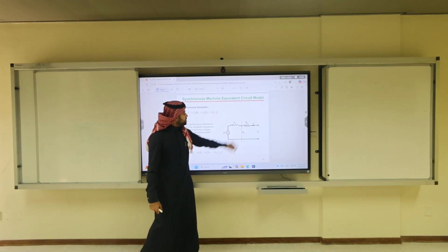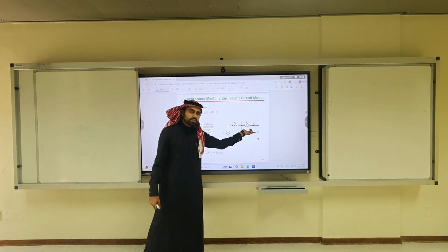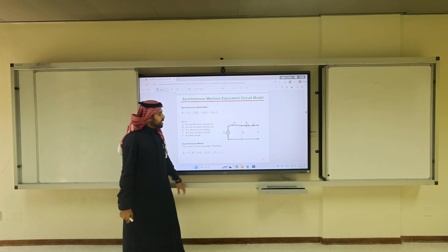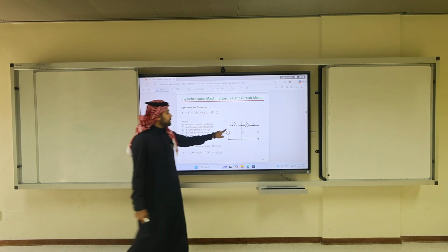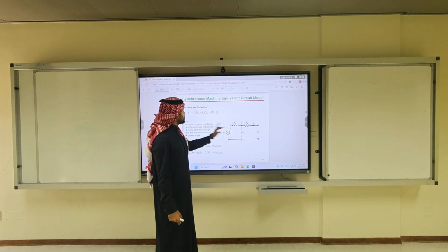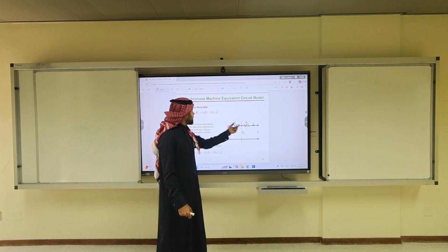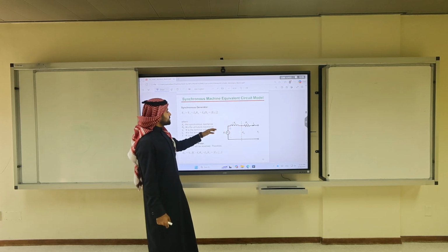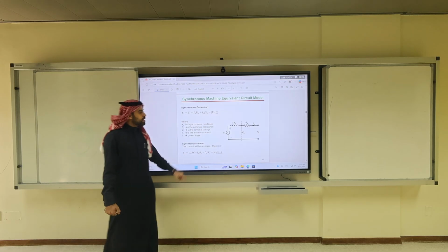And then we have R_A, which is the armature resistance. Sometimes we ignore the armature resistance. And then you have the terminal voltage V_T. So what's the formula? If you do KVL, voltage rise, E_F equals V_T plus I_A times (R_A plus jX_S). Sometimes we refer to it as E_F at an angle delta.